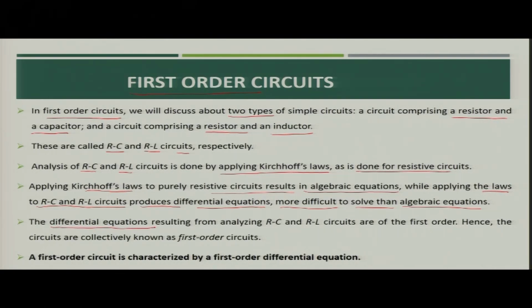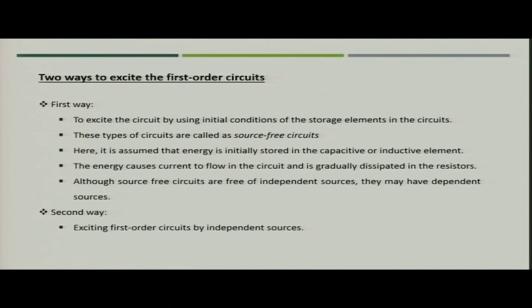Now, the differential equations resulting from analyzing the RC and RL circuits are of the first order. That is why we call these types of circuits first order circuits. So, we can say that a first order circuit is characterized by a first order differential equation. Wherever you see a first order differential equation, we can say this is a first order circuit. Now, we have two ways to excite these first order circuits.